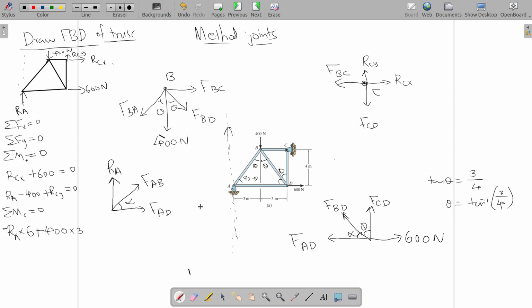And 600 Newton, you have 600 Newton external force, next external force. So you have total of 1, 2, 3, 4, 5 external forces. You have to consider all external forces. You don't need to consider internal forces, remember. So 600 multiplied by, what is the distance between line of action of 600 and point C? That is 4 meter.